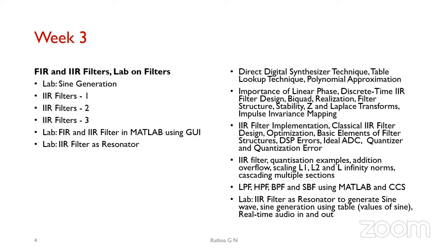So we have checked that using sine wave generation, so that whatever frequency I want to generate, I'll be giving the coefficients for it, the A and B coefficients, if you have seen the equation, and then the filter is going to oscillate and give me a sine wave through that. This is the best way of doing it in hardware, because it's going to consume very little time.